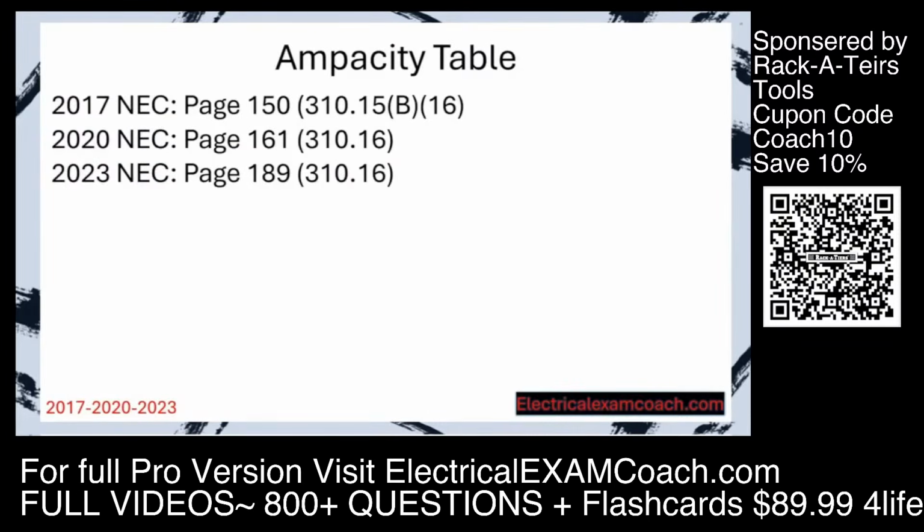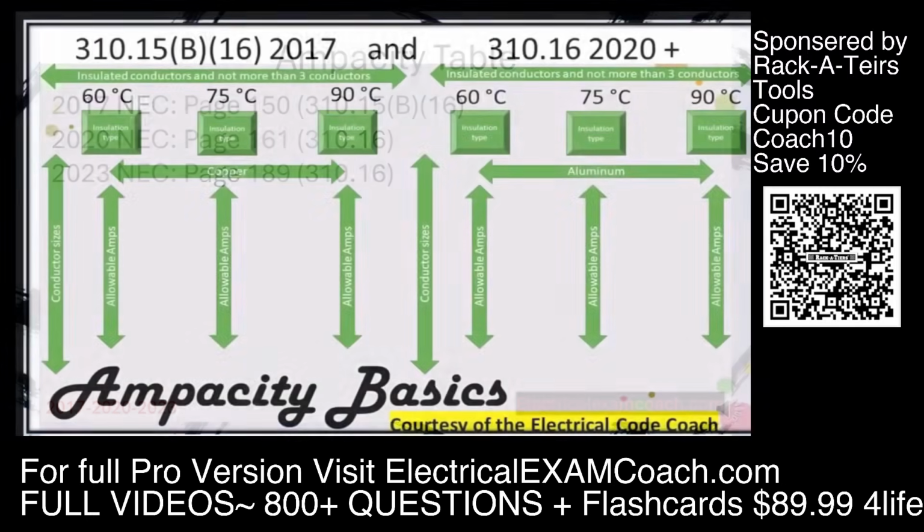Now let's learn about our primary ampacity table. If you're in the 2017, it's table 310.15(B)(16). And in the 2020 and later, it's table 310.16. Same information, new name. If you're in a softbound NEC, these should be your page numbers depending on what print of the NEC you have, whether you got the first round or second round print, but this will get you close enough. The most important thing is read the title of the table and make sure that it matches the actual table number.